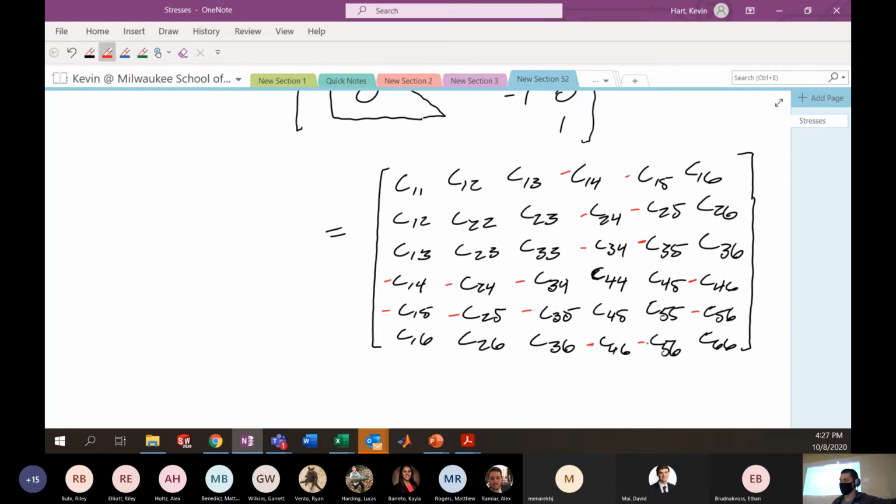After this rotation, we have all these negative numbers here. But we know that this stiffness matrix, this 6x6, has to be equal to our original stiffness matrix, because by a plane of symmetry the current configuration, the 0-degree orientation, has to be the same as the 180-degree orientation.